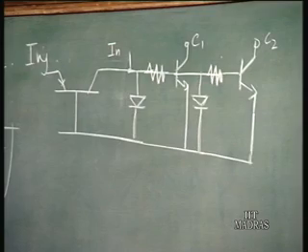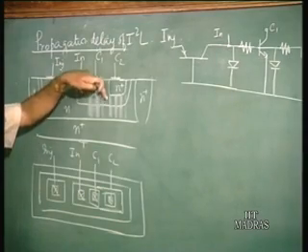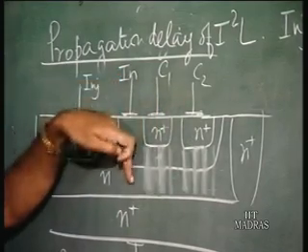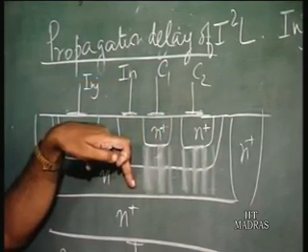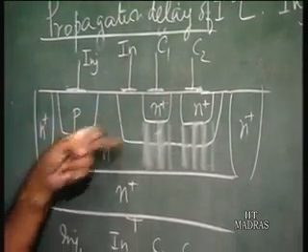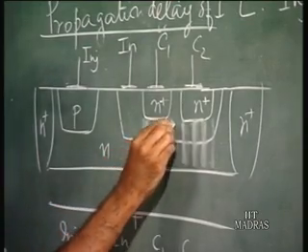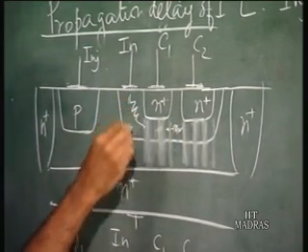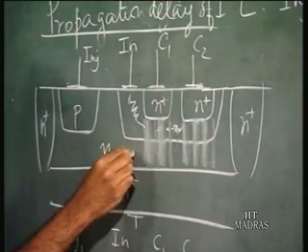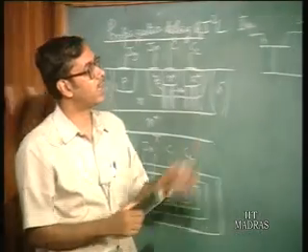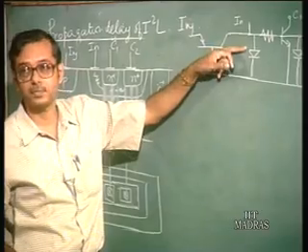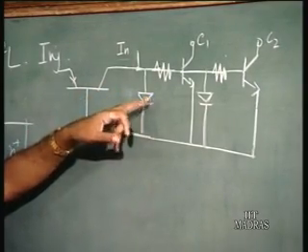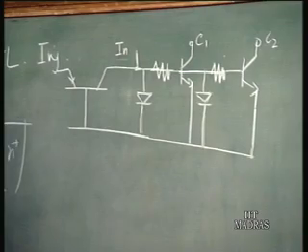These diodes, you see in these regions, this is a PN junction diode. So this is a PN junction diode here. You not only have series resistance, say this is a series resistance here from here to here, but you also have PN junctions here. So whatever current flows in here, part of it is getting wasted because of the PN junction here, and also you have series resistances.